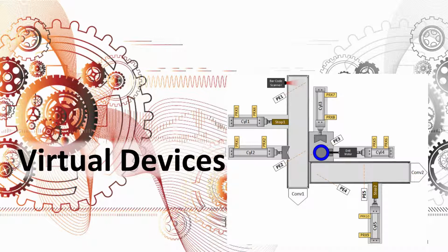So if the cylinder is retracted and you shift the spool, it moves the pressure to the piston side and allows the rod side of the piston to evacuate the cylinder, and it extends, and vice versa. When you de-energize a single solenoid controlled cylinder, then a spring returns the spool in the valve, and now you're putting the pressure on the rod side and you retract the cylinder.